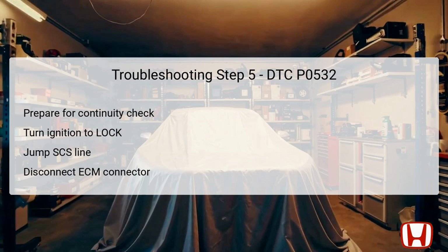By preparing the system in this way, technicians can better assess the electrical pathways connecting the AC pressure sensor to the ECM. Ensuring correct ground connections is vital for proper performance. This step establishes a solid pathway for verifying whether signal and power lines are intact between the AC pressure sensor and the vehicle's control modules.